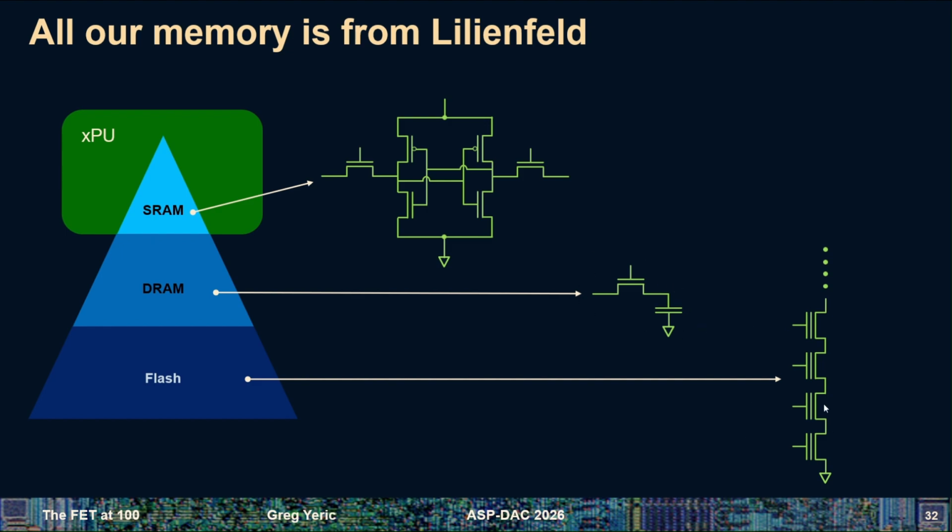And then the last one is flash. This is ingenious, where you are tunneling electrons from the channel up into a floating gate. This is a piece of silicon that's not connected to anything. It's sandwiched between two dielectric layers, so between the gate electrode and the substrate there is a metal or polysilicon feature, a dielectric, another floating gate, another dielectric, and then the channel.